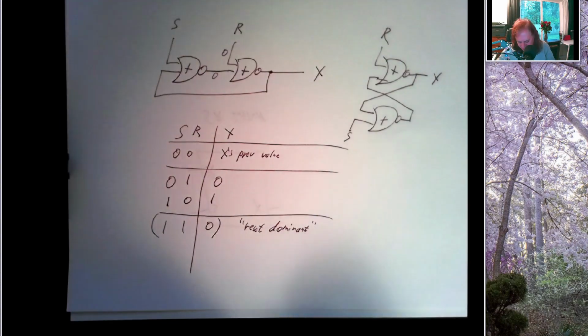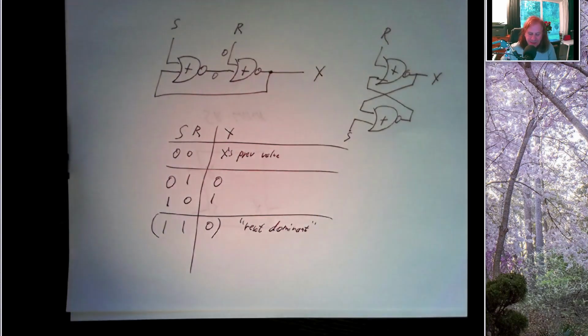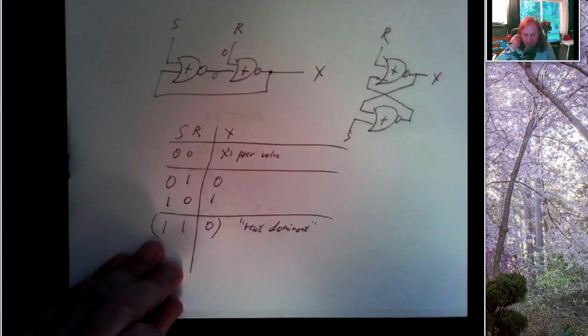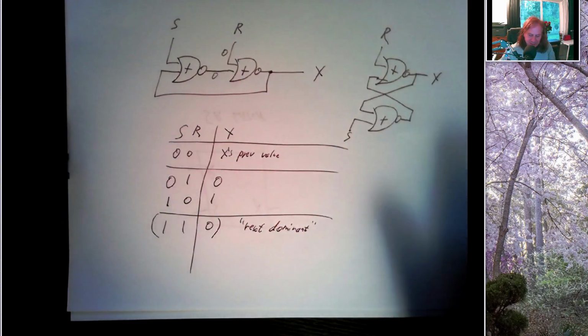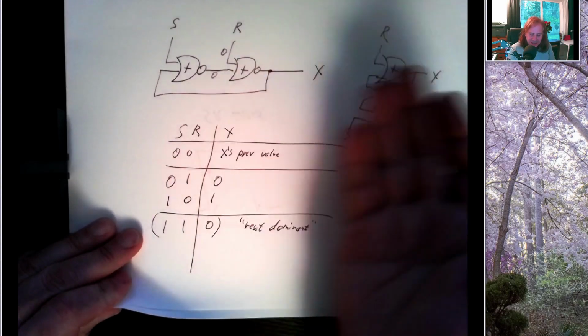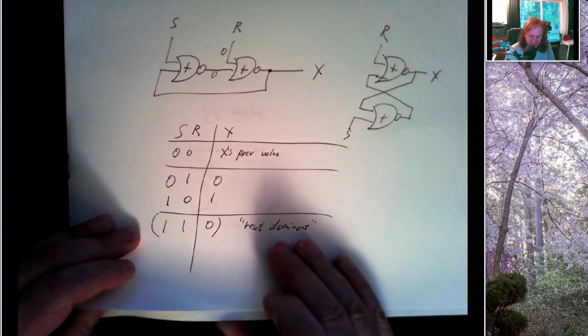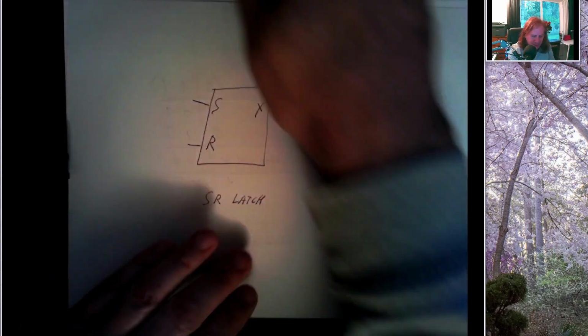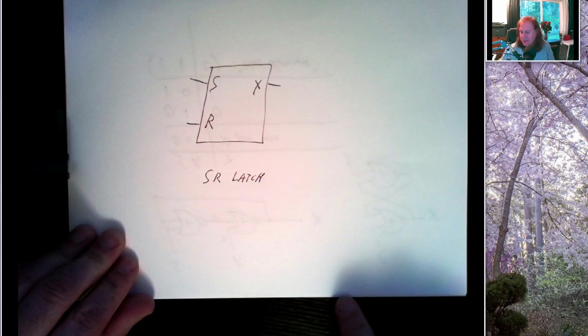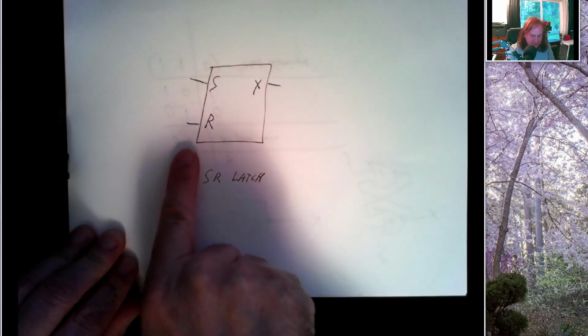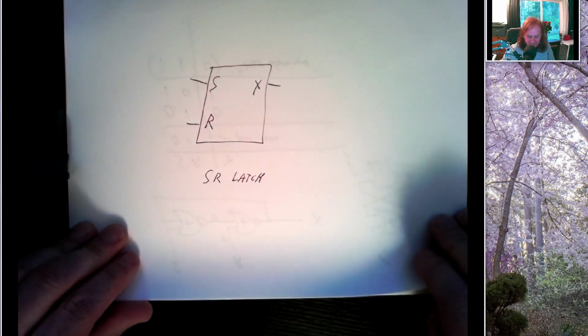So we saw that when we looked at the schematics for the Apollo guidance computer. There are a bunch of pairs of these cross-coupled NOR gates. It's exactly the same circuit as that, just drawn differently. But this is the conventional way of drawing it. All right, so we have an SR latch. It's a device that we can set or reset by either making this line high or making that line high.